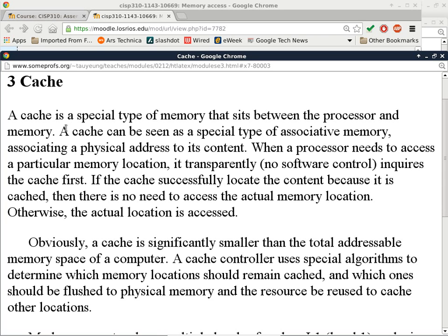the processor. But why don't we make cache external to the processor then? Then we can have additional chips to implement cache just like the good old days. What is the downside of that approach? It would be much slower, because now you have to run longer traces to the cache. And remember what a trace is. It's a capacitor, it's a resistor, it's an inductor. The longer the trace, the more effect it will have in degrading the signal, and the more you have to slow down to make sure that you're reading the correct information from that device.